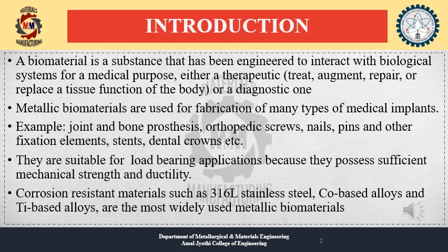Metal biomaterials are used for fabrication of many types of medical implants. Examples: joints, bone, prosthesis, or orthopedic screws, nails, pins, and other fixation elements, stents, dental crowns, etc. They are suitable for load-bearing application because they possess sufficient mechanical strength and ductility. Corrosion-resistant materials such as 316L stainless steel, copper-based alloy, and titanium-based alloy are the most widely used metallic biomaterials.